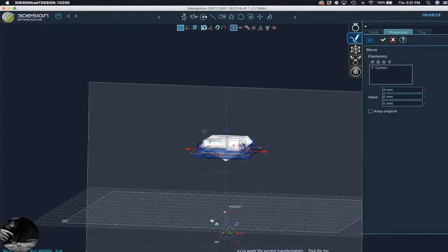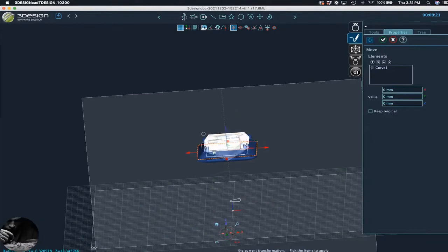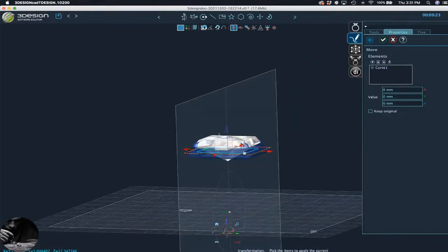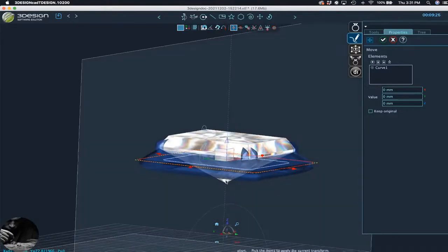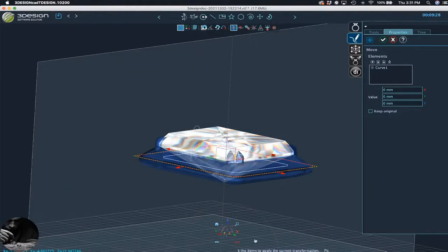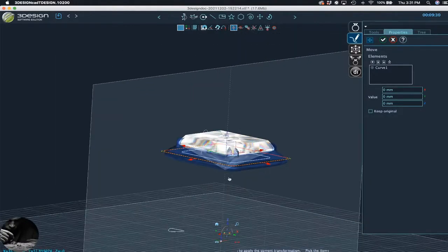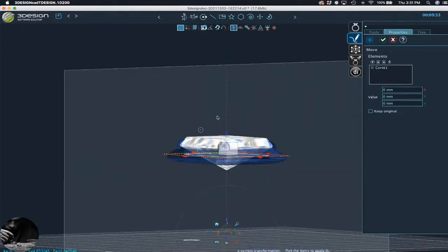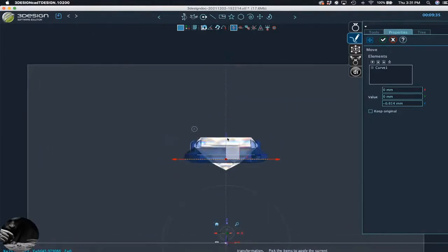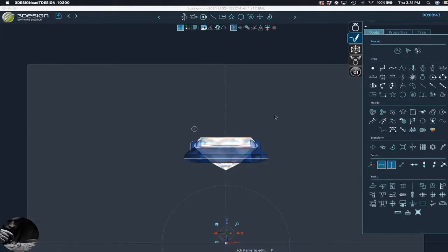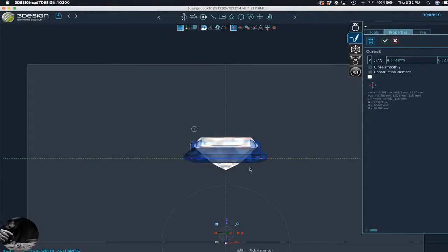It's okay to draw on the central plane and then pull it up, but when you get into more complex geometries, it makes it so much easier to have your line right there live where you're trying to work, rather than messing with it down there and trying to figure it out. But anyway, getting a reference point here, you see how I put that angle there? Well, I want to make my next halo, so I want to use that and just keep this one live. Now these are not going to have a memory to one another, so if I modify that, it's not going to change this, which is cool. If I wanted to do that, then we can go into the move tool.